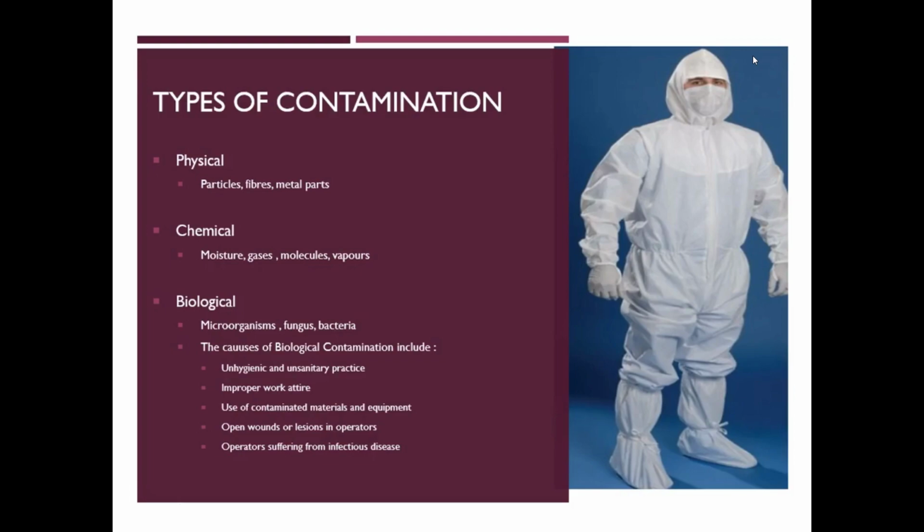For biological contamination, we talk about microorganisms, fungus, bacteria. An obvious example would be improper cleaning of equipment, or use of unclean equipment for sampling or during the process. Bacteria may thrive if the container is not properly cleaned and dried. The contaminated container will then affect the product, and microbes may thus be introduced into the batch.